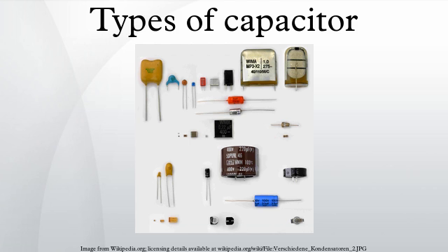This behavior is a small source of nonlinearity in low distortion filters and other analog applications. In audio applications, this can be the reason for harmonic distortion. Film capacitors and electrolytic capacitors have no significant voltage dependence. Voltage dependence of capacitance for some different Class II ceramic capacitors.